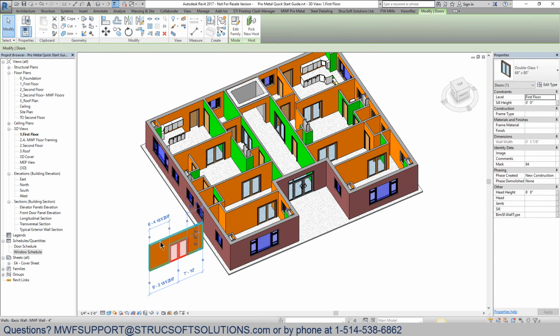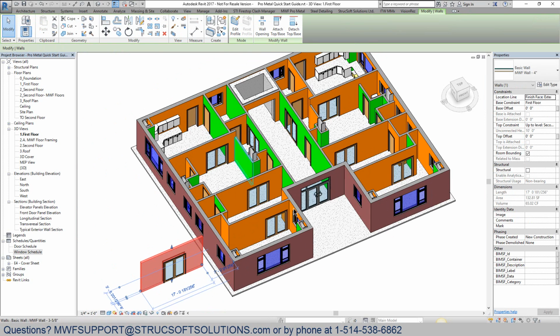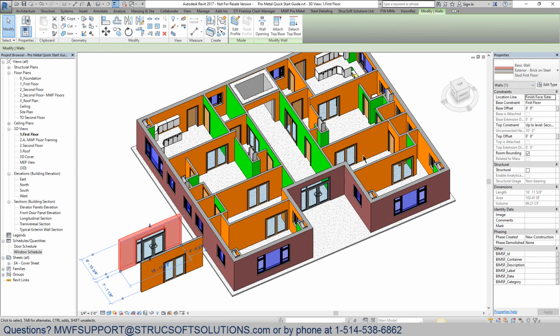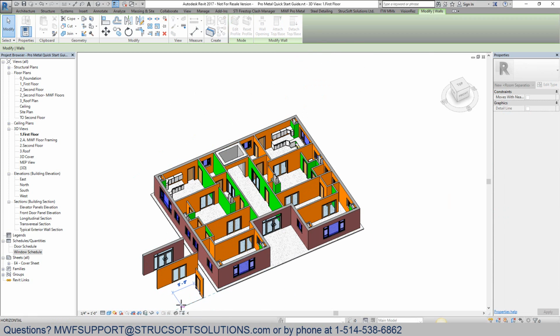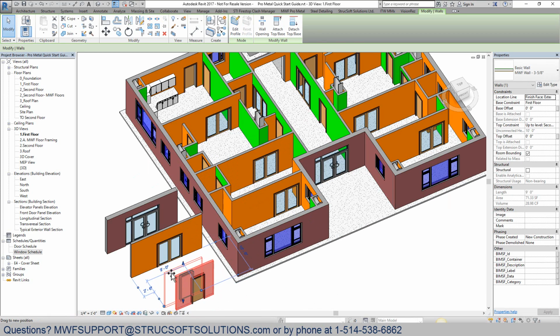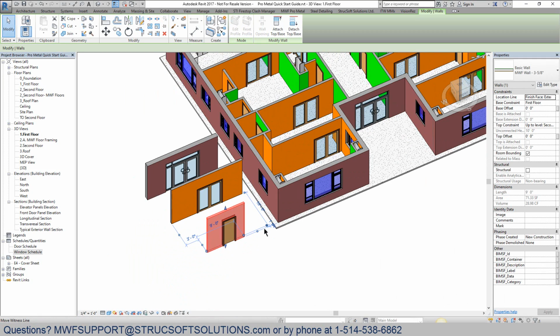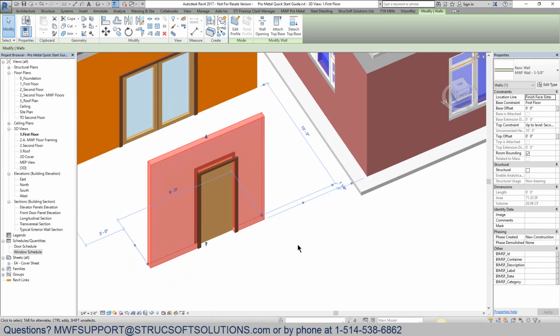So we've got a 4-inch wall. We can take a 6-inch wall, copy him over here, and let's find a 3 5/8. I believe this guy was right here. Perfect. There we go, just like that. And we'll straighten them out too. Great. So we've got our 3 wall types over here on the side. We're ready to start creating our templates.